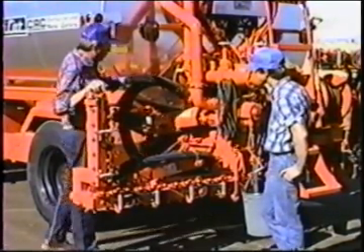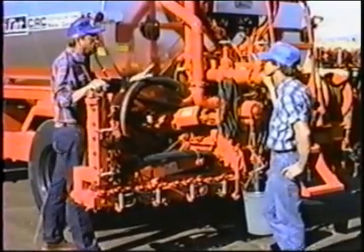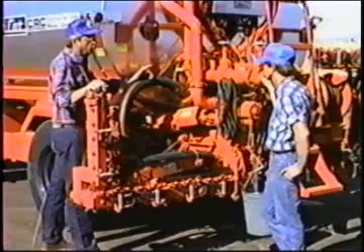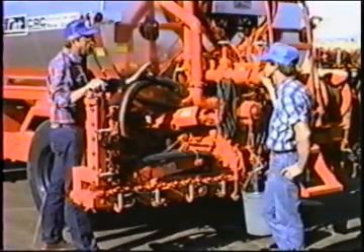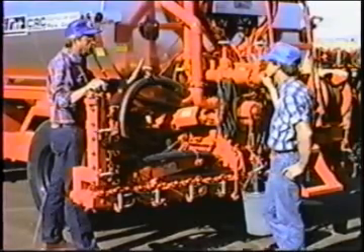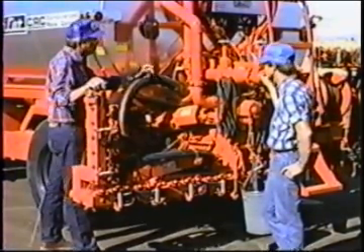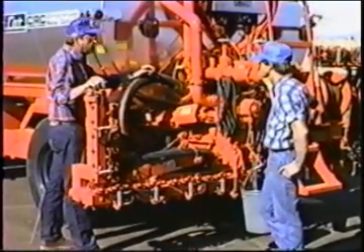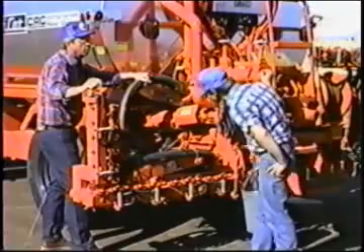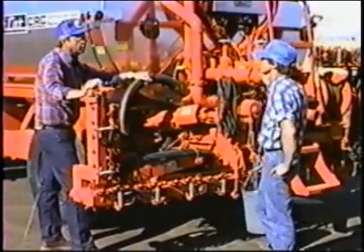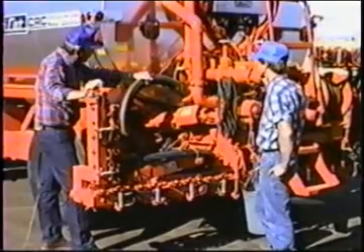The computer sees three things. It sees the desired spread rate, that is, into the computer we are going to tell it what we want. We're going to say we want 0.3 gallon per square yard, and we'll get into that when we get into the cab and look at the computer and the switching. The computer reads the travel speed of the truck from a gear tooth sensor on the rear end housing of the truck. That is, we count the teeth in the ring gear on the main rear end.